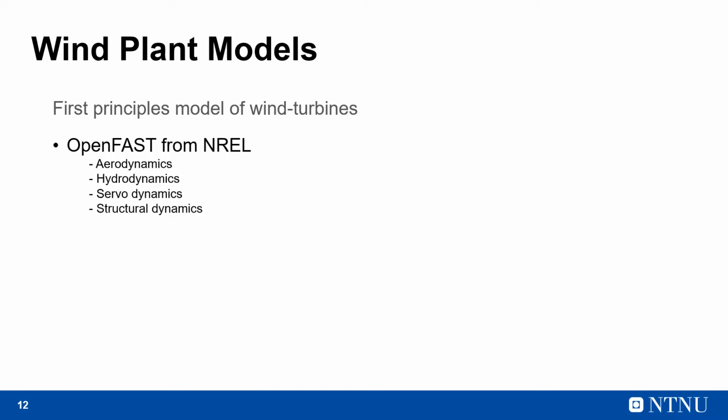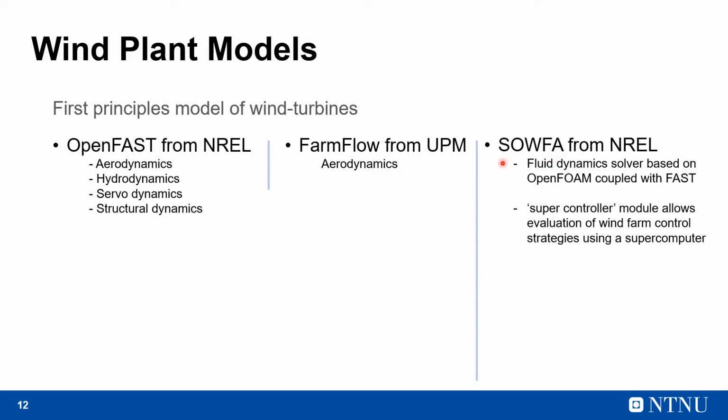Looking at the first principles models of wind turbines, there is OpenFAST from the National Renewable Energy Laboratory, which has modules for aerodynamics, hydrodynamics, servodynamics, and structural dynamics. Looking at FarmFlow from the Polytechnic University of Madrid, it has a module for aerodynamics. And SOWFA, simulator for offshore and onshore wind farm applications, again from NREL, is a fluid dynamics solver based on OpenFOAM coupled with FAST. It also has a supercontroller module which allows for evaluation of control strategies using a supercomputer, but I read that to simulate almost 30 minutes, you need a day.